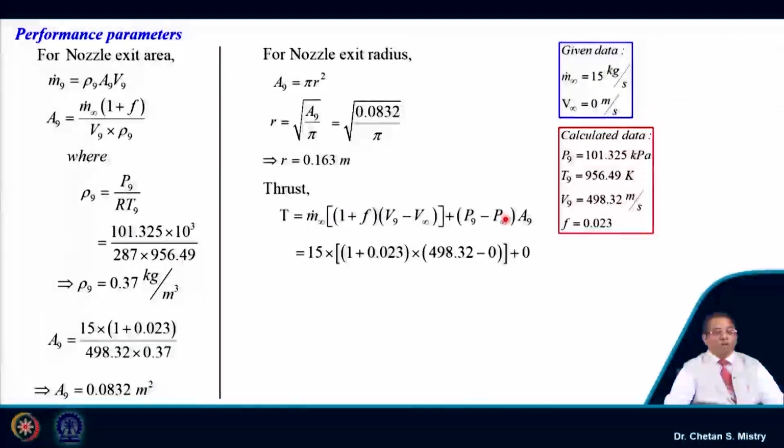If you recall what we mean by unchoked nozzle and choked nozzle, that is what will be making impact here on thrust calculation. So, by mistake, if we do our calculation for critical pressure ratio wrong, there are chances that we will come up with the wrong number for the thrust. Okay. Now, if we put all these numbers, it says my thrust is coming as 7646.72 Newton.